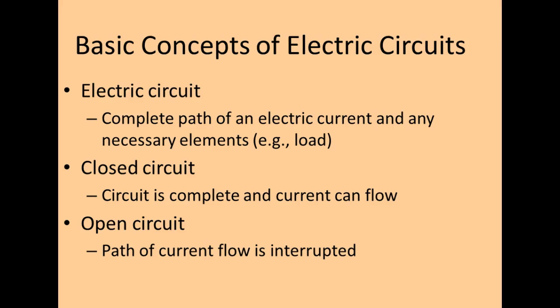But there's a common theme running through here, y'all. Additive, additive, additive. Series. Amp draw is the same. Amp draw is the same. Another thing is, on a series circuit, what happens if there's an open in the circuit? That's right. That's what makes it a good safety and a good control. Nothing runs unless we have everything in order. And for safety, if anything opens up, it cuts it out of the system.